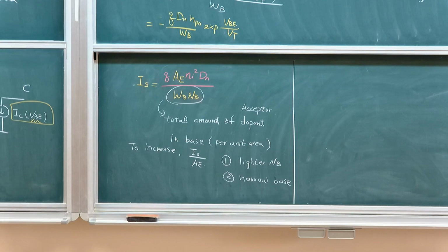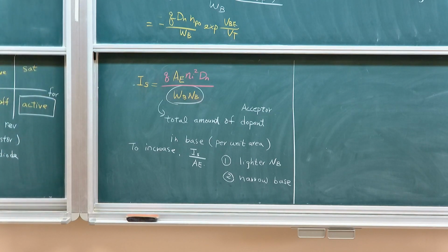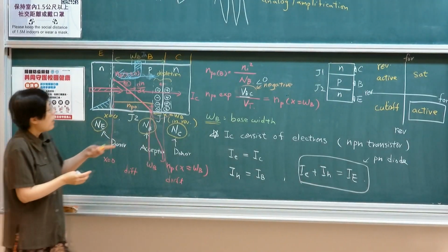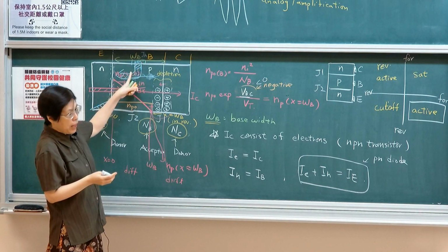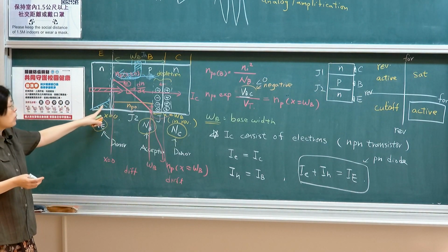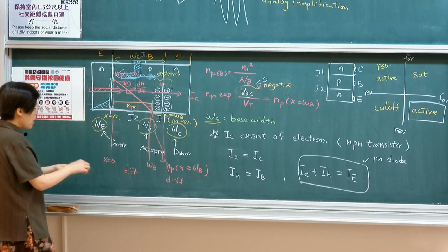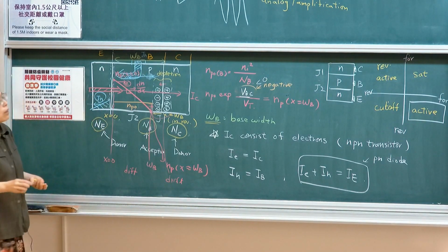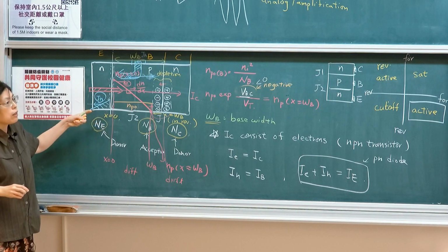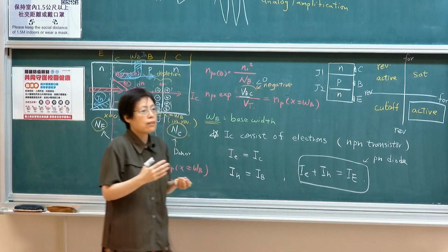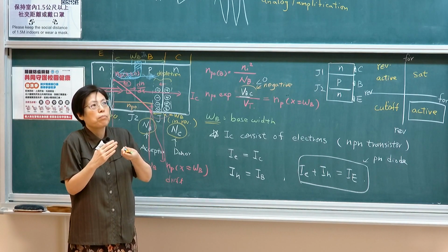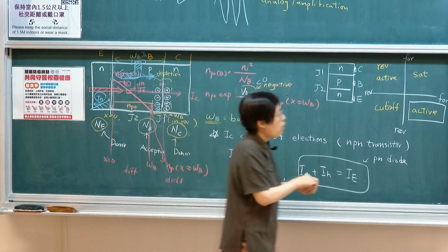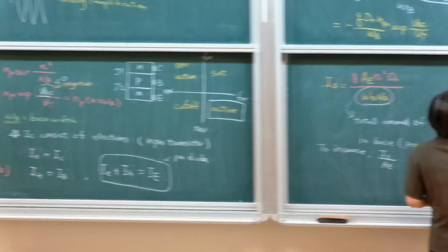As I already highlighted here, a bipolar junction transistor functions as a current splitter. It will split the electron current and the hole current. And the hole current will be coming in from the base and then flow into emitter. So the emitter diffusion itself will then limit the amount of hole current. So this will determine the amount of hole current. So we're going to do the same exercise on the emitter side. This is like separating the discussion of a forward-bias p-n junction. You discuss the electron and discuss the hole. So the hole current we look at.